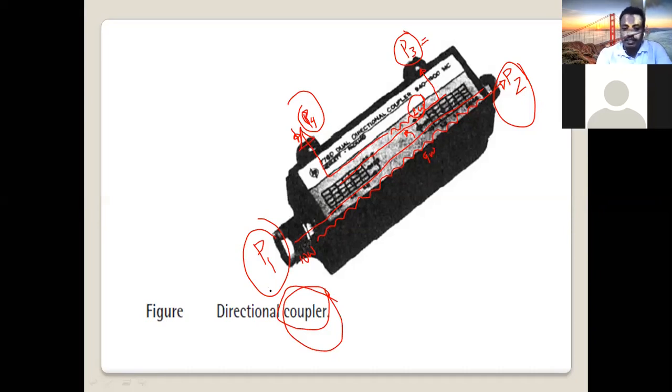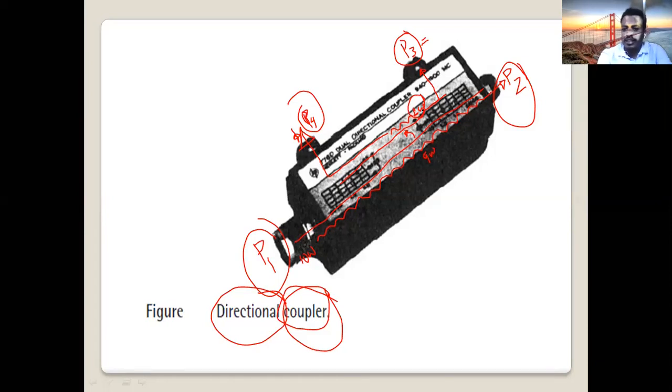When directional couplers are designed, as the name indicates, they are directional. Directional indicates what? The coupled signal, the 1 watt transferred signal, should be transmitted only to port 3. We have to get 1 watt here, right? But a small part of the signal will go in the wrong direction and go to port number 4, which is called the isolated port.